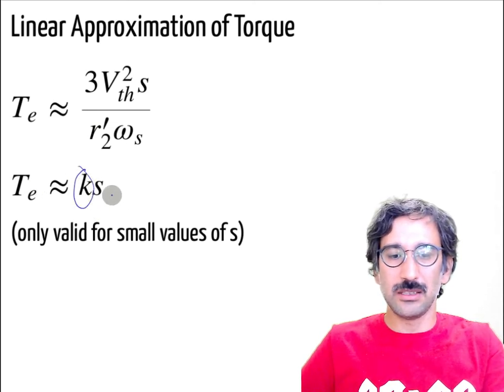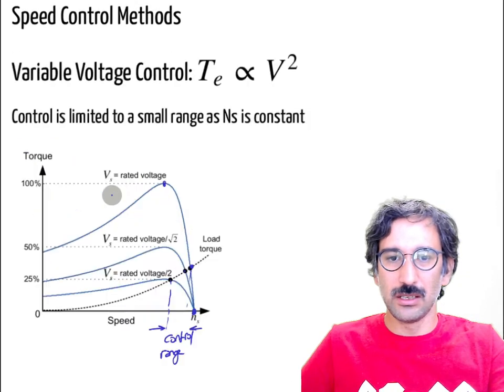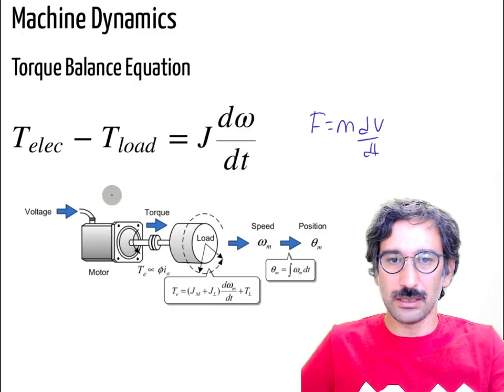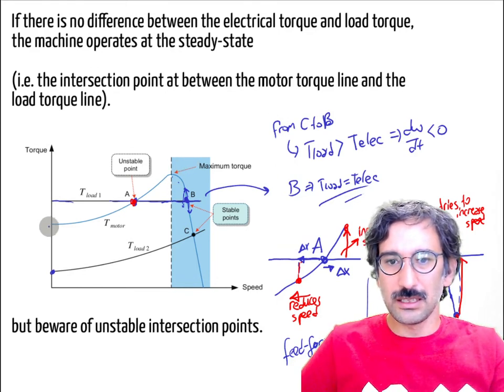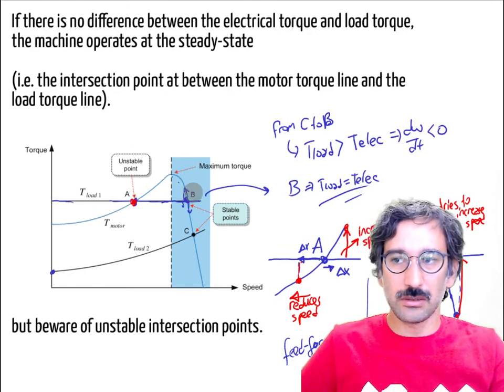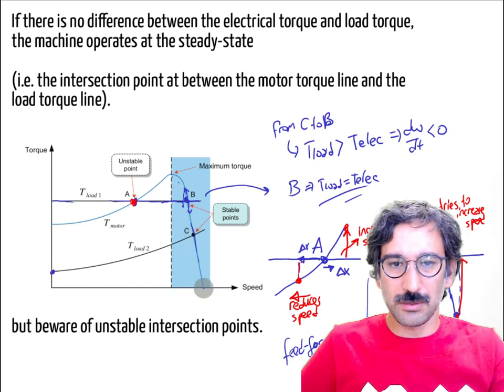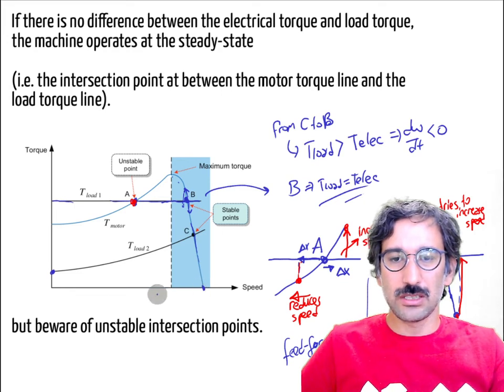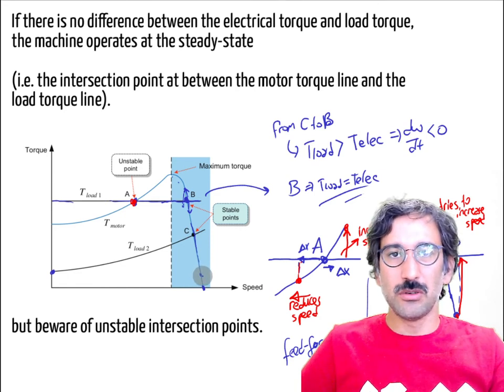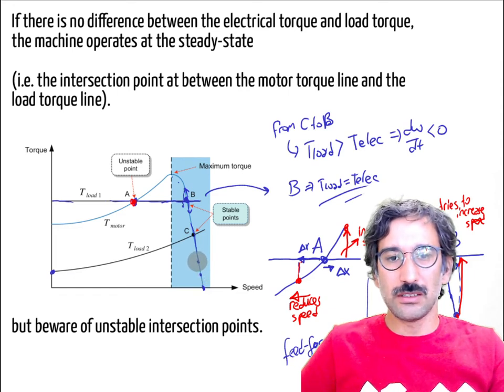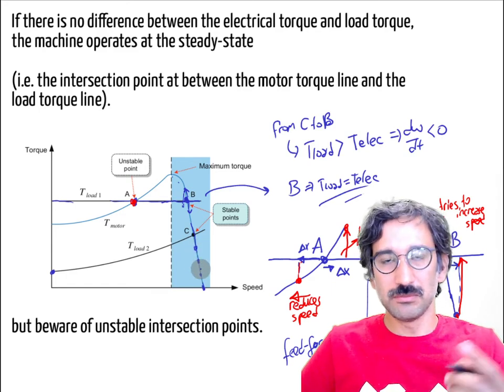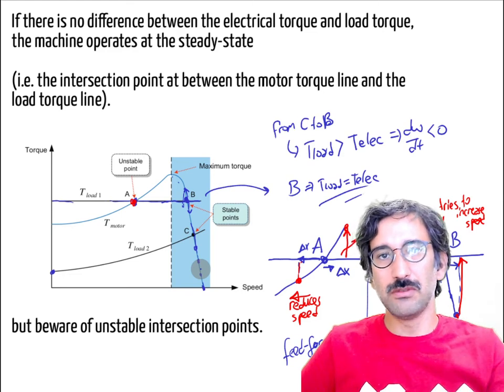Okay, so it is kind of linear, and actually you can see it maybe in the torque characteristics curve. Let me go back quite a lot. Okay, for example here you can see, yes, you have some fancy lines going out like that, but as you go to the synchronous speed, that one is kind of linear. So that means when slip is 0, you are generating 0 torque. If slip is 0.01, you are generating some torque. If slip is 0.02, you are generating twice of that, etc. Okay, so if you double the slip in that small operating range, torque will be doubled.